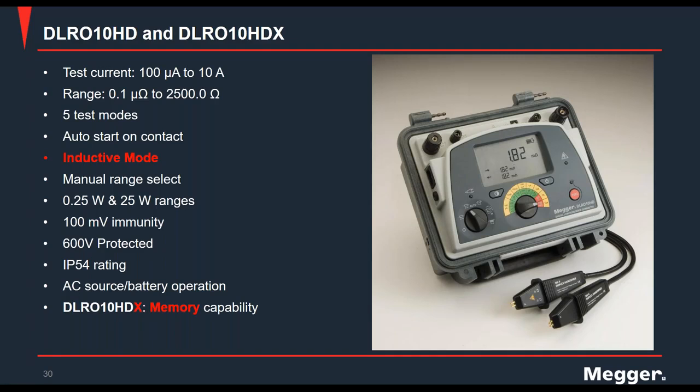One is the lower power mode at 0.25 watt, and then you have the higher power mode that goes up to 25 watts. Then the device has 100 millivolt immunity to background noise. It is 600 volt protected. It's IP54 rated. It can be charged using an AC source and is battery operated. Now, if you see yourself using the DLRO 10 HDX, that has memory capability.